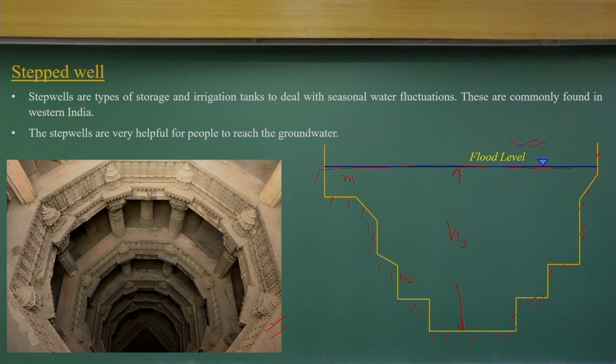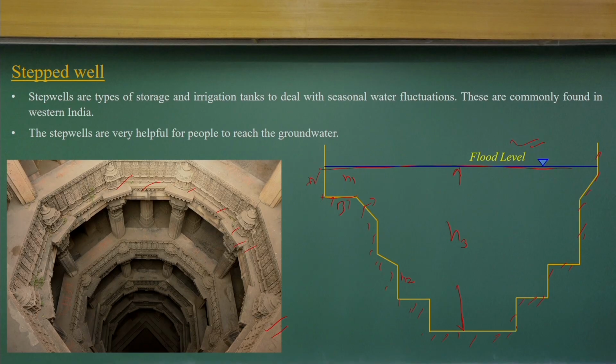And how have they designed it? What is the water pressure acting on this surface, surface A, surface B, one horizontal, another vertical, another inclined, and there could be curved natures, curved projections and all. How much water pressure acts when the well is in a completely filled condition? Very interestingly, when designing it, we need to determine the pressure force acting on the vertical surface, horizontal surface and the inclined surface.